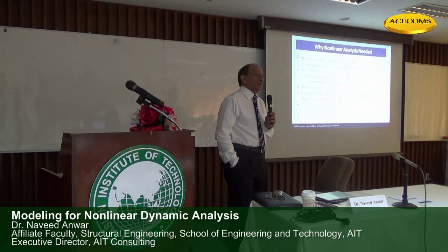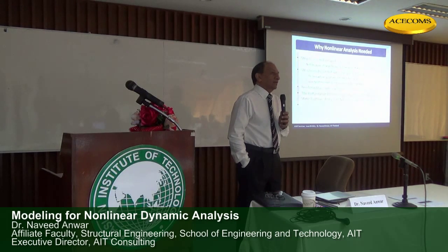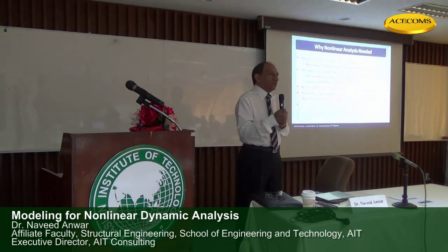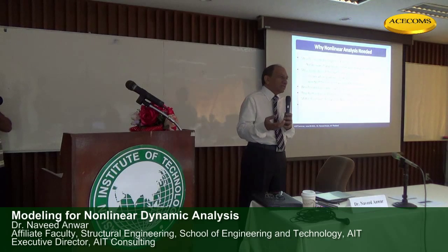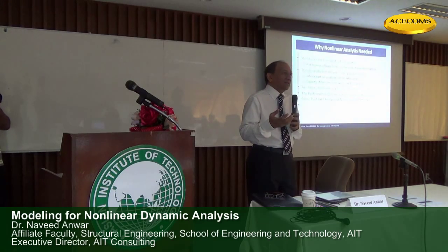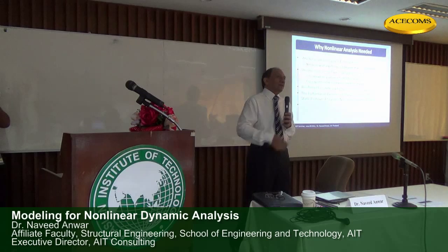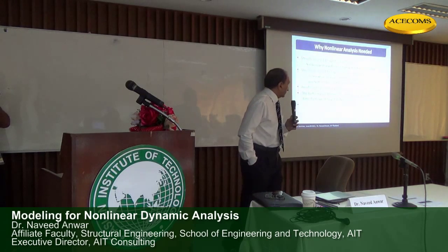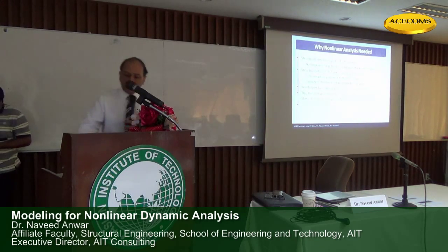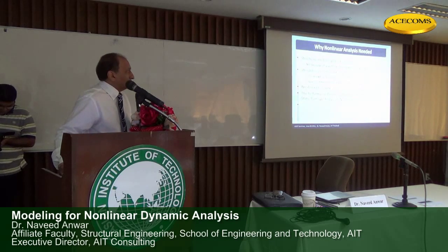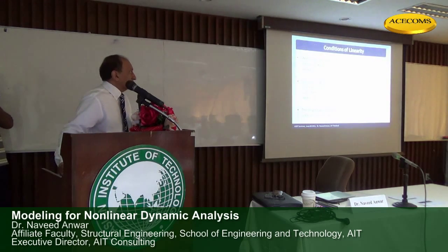Reinforced concrete especially is a highly nonlinear material. Why? First of all, it is many materials together, not just one material. It cracks, it damages, it disintegrates. In that case, using linear analysis is not reliable. So nonlinear analysis, for example pushover analysis and time history analysis, needs to be used.